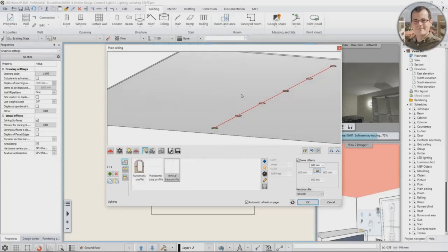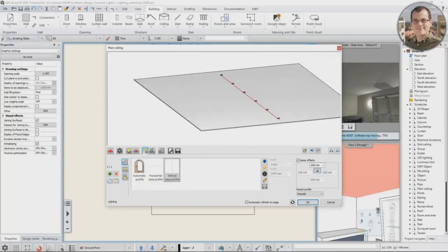So let me go back to the position. And here I can see a bunch of values and padlocks and whatnot. Let me show you how that works. First, let's disable this check mark and fix the value which is not going to be changed. And the rest of the values, I know that it's 500 from one of the sides and 500 from the two edges, which means that this assortment of lamps is going to be positioned from these sides for 500 millimeters.